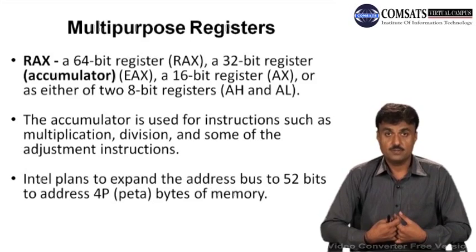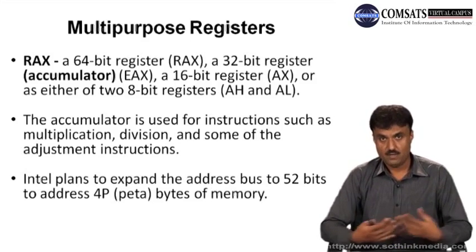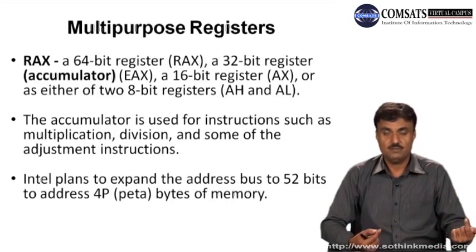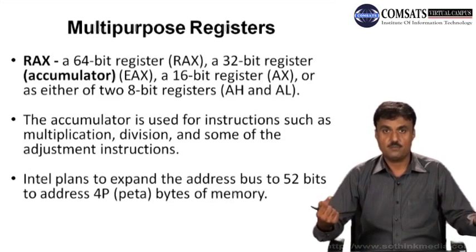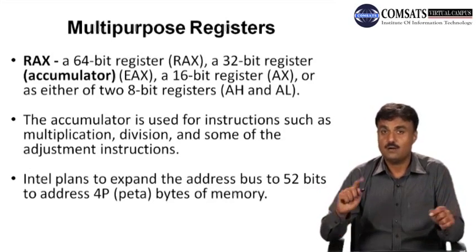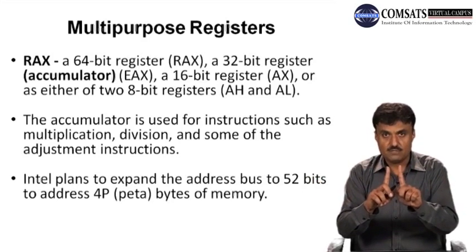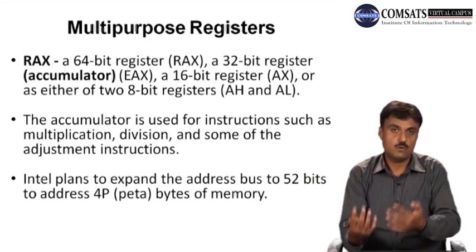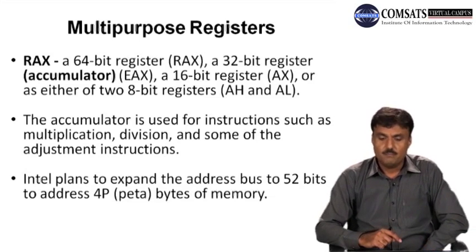This accumulator will also be part of the instructions where one value is stored in the accumulator and another value is stored in another register. We perform addition, subtraction, or another operation between the accumulator register and another register. Again, the two values of these two registers will be manipulated, and the result will be stored back in the accumulator.